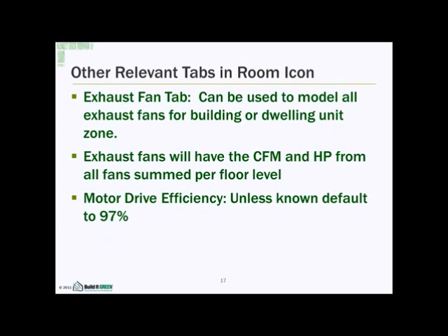tab. Sorry, I don't have a real clear slide on that tab. I couldn't fit it into the slide without making you all squint. If you have Energy Pro, or if you haven't looked at Energy Pro, you can always download it and run it without any modules, and you can see where the room icon and the exhaust fan tab is. But if you are familiar with Energy Pro, you should know where this fan tab is and what I'm talking about as far as the exhaust fans, horsepower and CFM.